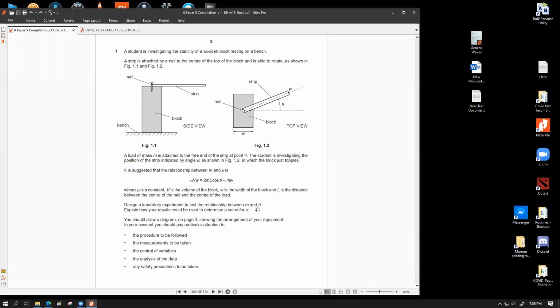Okay, and sir, how many readings do we have to take of W from the top edge, or we have to make the average? How many readings do we need to take? Well, to be honest, the more the merrier. But in this case, I wouldn't go for that. For example, the W is basically this dimension. So I would say, let's say we have 4 faces over here for this object where we can measure the W. So this is a rectangular block. So I can take 2 measurements of each side so that I can have 8 readings. Then I can have the average of 8. Do you understand how 8?